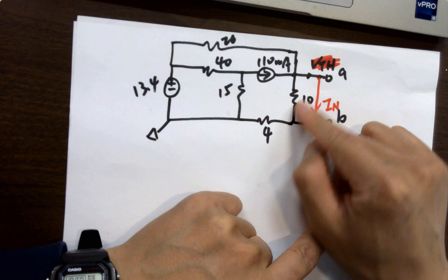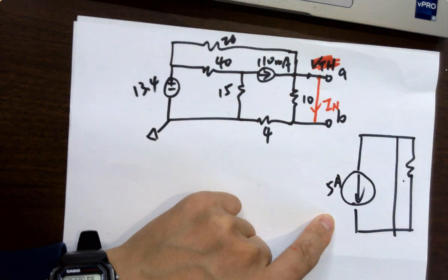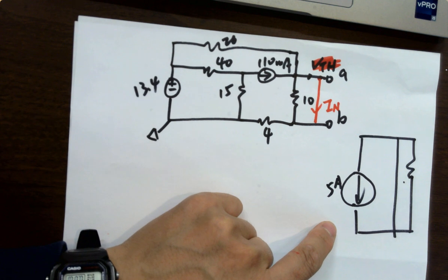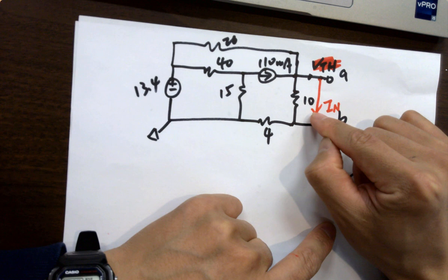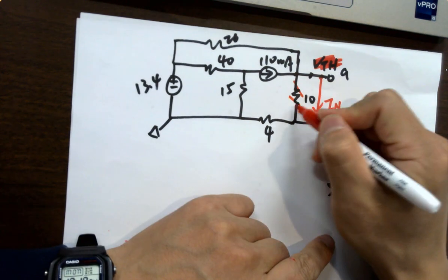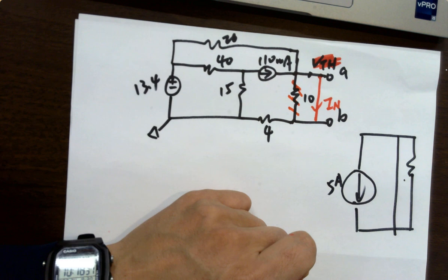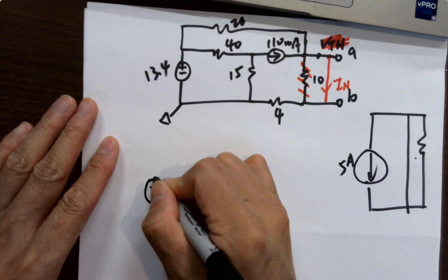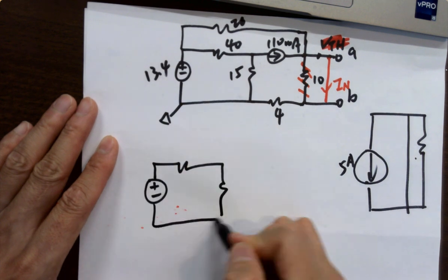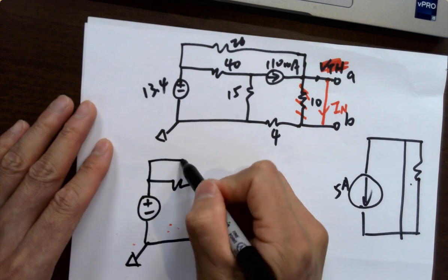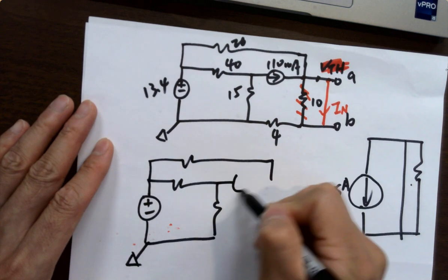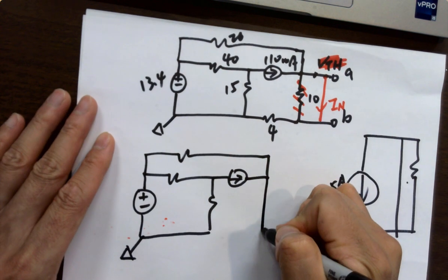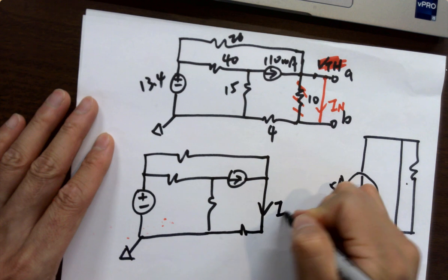So now you are pretty lucky you get a resistor. If you have a current source, making things complicated, you are asking, am I shorting the current source or not? You are not. Okay? But the resistor is going to be shorted. So what's happening to the resistor? It's gone. Right? So the circuit becomes, it's gone, only leaving a wire here. So that will be IN.